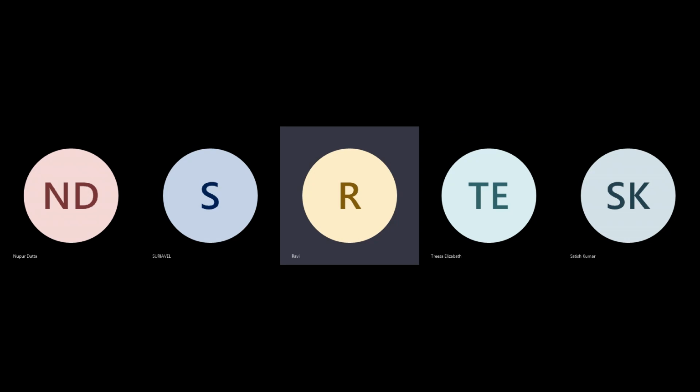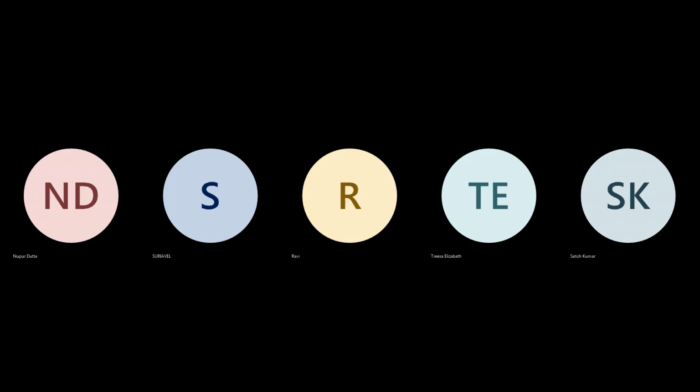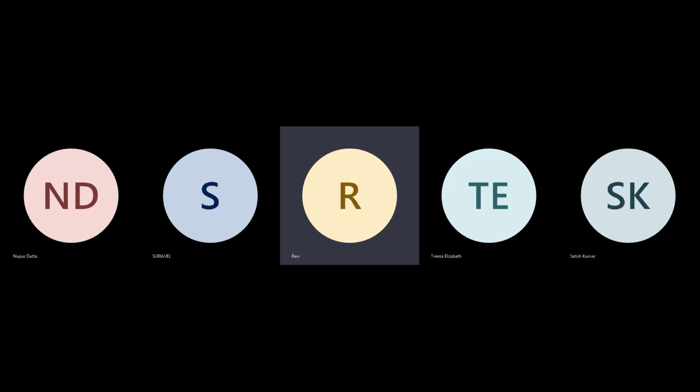Then automatically the idea of normal buffering goes to high fan out net synthesis, you understand, right? High fan out net synthesis will create something like a clock tree, in parallel, like a logarithmic scale, right? One buffer driving 16 or something like that. You have to set a default. For your PNR, you set maximum fan out 32.